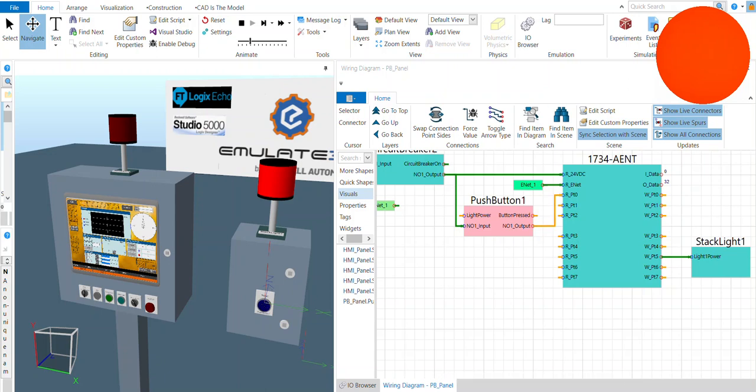So just to recap, having the ability to connect directly to the emulated PLC and to utilize E3D's ability to create standard panels gives us the capability to perform a level of virtual commissioning, thus giving us the opportunity not only to validate, but also alleviate any logic or wiring issues before starting up the physical equipment.